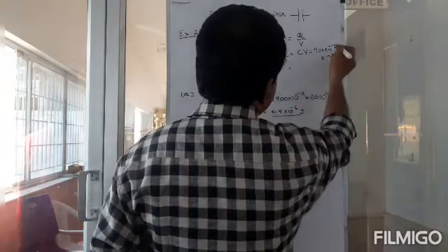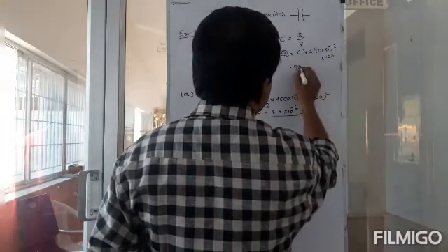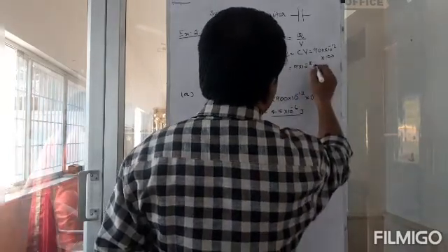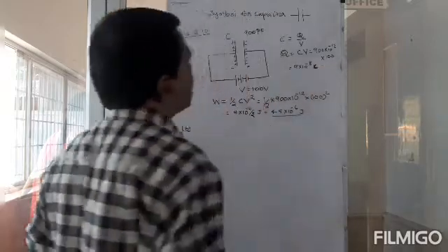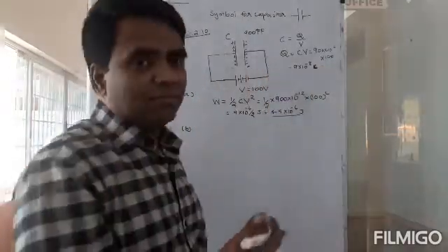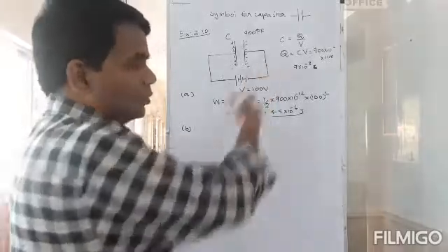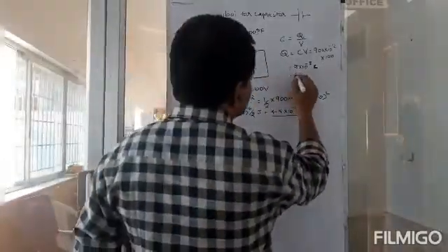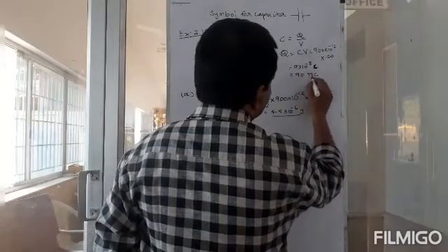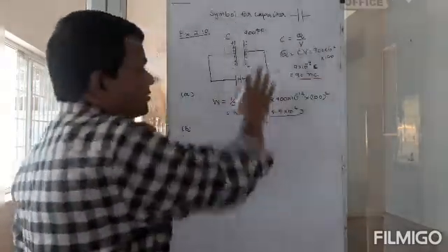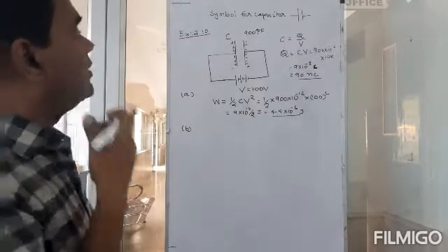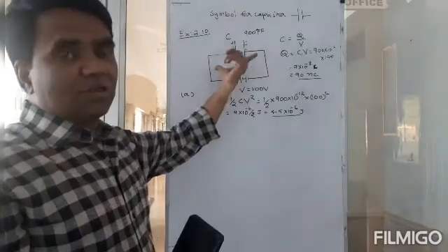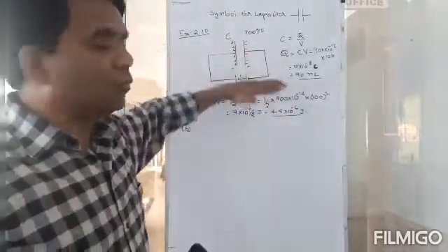So that is going to be equal to 9 into 10 power minus 8 coulomb. So I can say it's 90 nanocoulomb. Okay. So we'll just leave it like that. I can also calculate the charge there. Anyway, so you have the charge, you have this capacitance. So the voltage across the capacitor will be 100 volts right now.